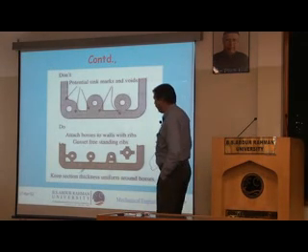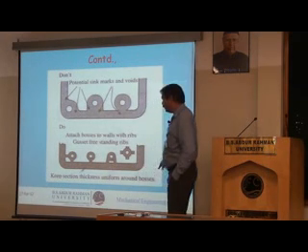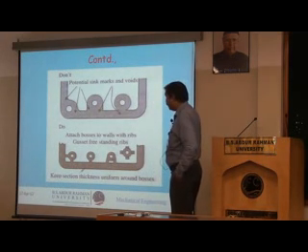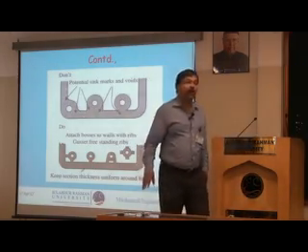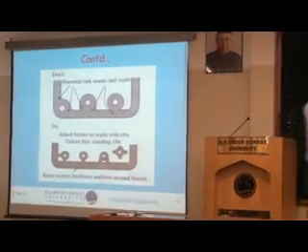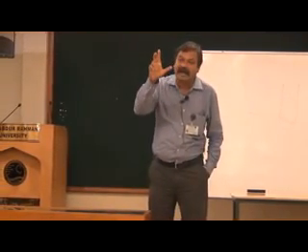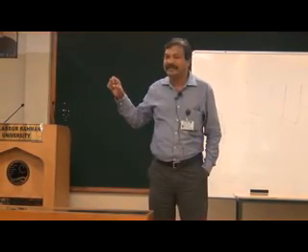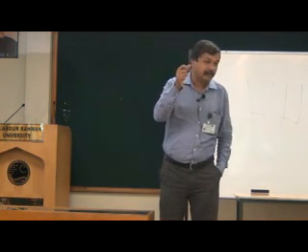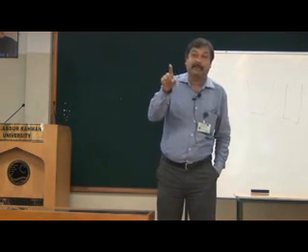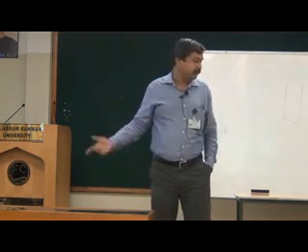So when you have bosses, these are called bosses, you should position them carefully. Okay, and you should keep the section thickness uniform around bosses. What will happen if the section thickness is not uniform? The section thickness is large at some place, and very small in some other place. If the section thickness is very large in some place, then there will be molten metal remaining in that place because solidification would not be complete.